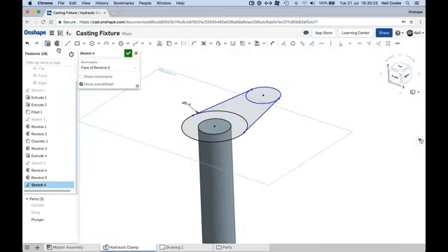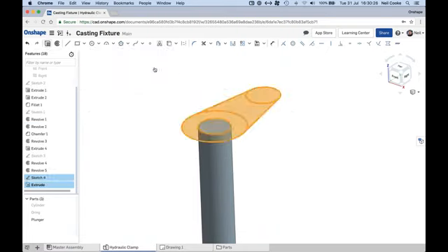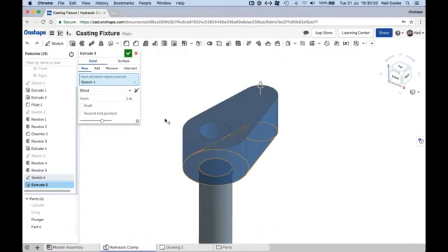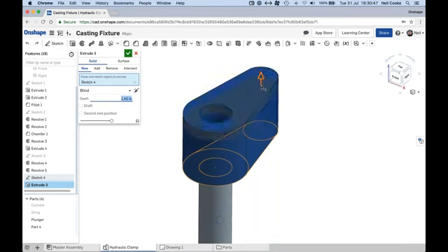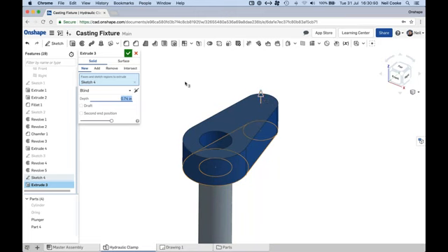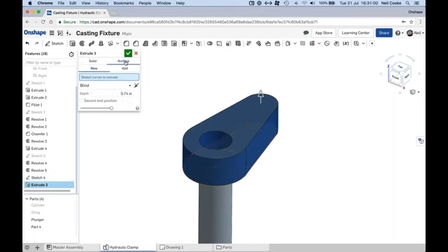So, for example, here now, if I go ahead and hit the extrude button, you'll see that even though I didn't trim the sketch back, it worked out the individual internal contours and therefore created a hole here. Let me just make that full. So you created a hole here and not over here. And you also get a little drag handle to actually change the size, which is fine. But in the same way that we have in Creo, you can build every single type of feature from one extrude command. So we have solids, we have surface.